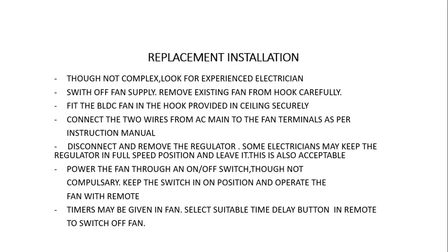Disconnect and remove the regulator. Regulator is not required for this fan. Remote control is the regulator for this fan, so you don't need a regulator. You can remove the regulator and short the wires. Some electricians may keep the regulator in full speed position and leave it as it is. This is also acceptable. So power the fan through an on-off switch, though it is not compulsory.